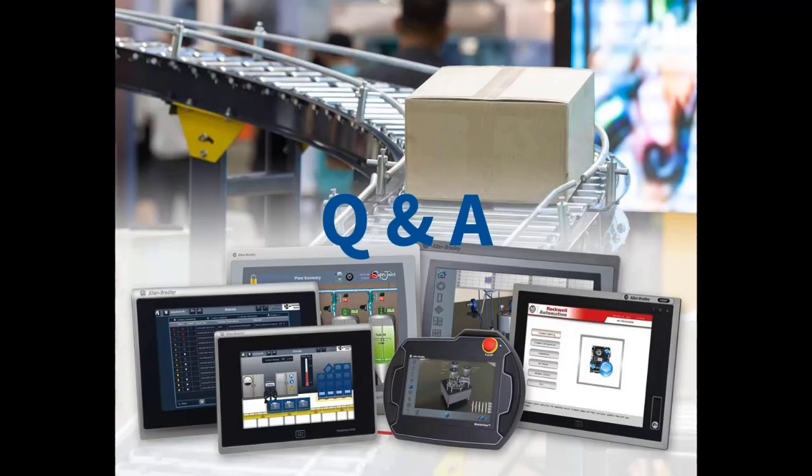Thank you, sir. And how does the VNC work when using it the first time? Derek, I believe that's another question. Yeah. Setting up the VNC is super easy. If you're pulling this out of the box, there's just a setting in the settings menu that you can enable, either full control or just view, and then you are required to have a password set on your program. So you create a password in View Designer and turn on the option on the PanelView, and it only takes a minute to get up and running.